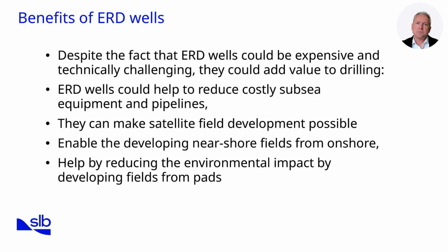Extended reach drilling wells bring several important benefits despite their higher cost and technical complexity. First, ERD can reduce the need for subsea equipment and pipelines. By drilling long step-outs from a central facility, we avoid installing subsea trees and flow lines, which reduces capital expenditure and operational risk. Second, ERD wells enable satellite field development. Marginal or stranded reservoirs that are uneconomical to develop with standalone platforms can be reached cost-effectively from existing facilities.